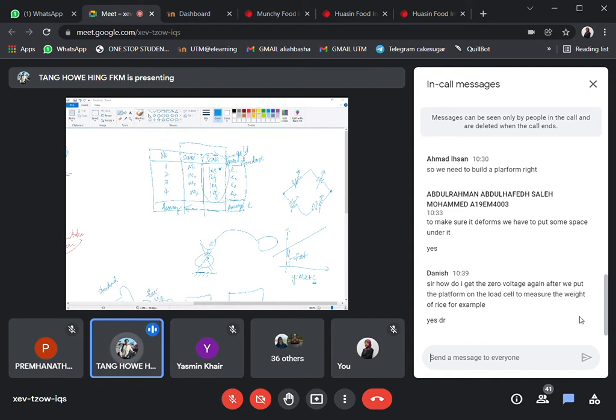Okay, so that means later on when you are doing the reverse, you just use the same formula and rederive for x. It will be something like y minus c and then divide by m. So this automatically will get rid of the effects of the offset.